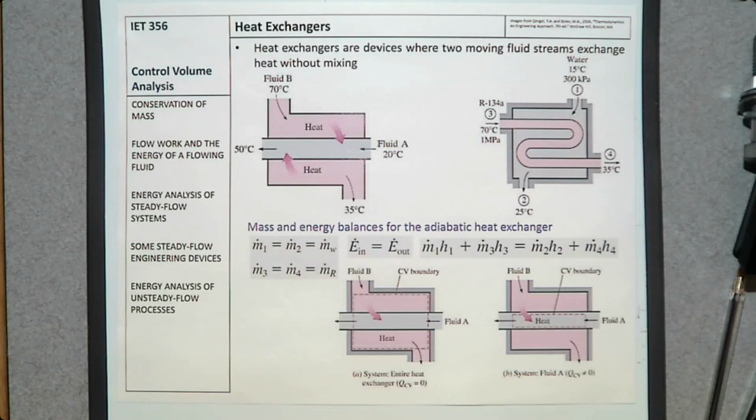And this is the simplest schematic to show a heat exchanger. But if you design a heat exchanger in this way, you're not going to find a job. The reason is, what do we want? We want to exchange heat, and the heat transfer occurs on the interface between two fluids.